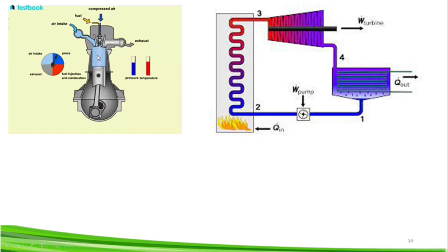At state 3 to 4, the isobaric process, fuel is added, and the combustion occurs due to high temperature while maintaining a constant pressure because the volume is also increasing. While at state 4 to 5, the adiabatic process also, in this process expansion takes place.